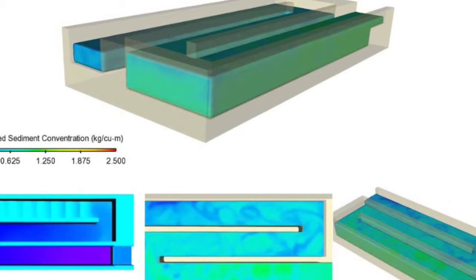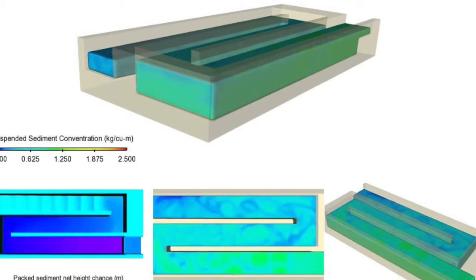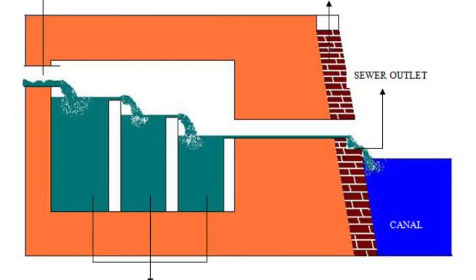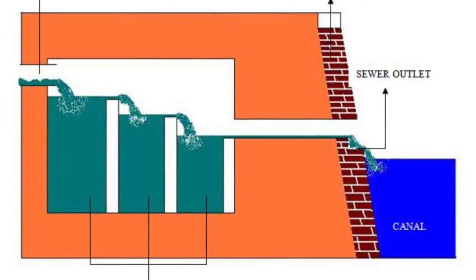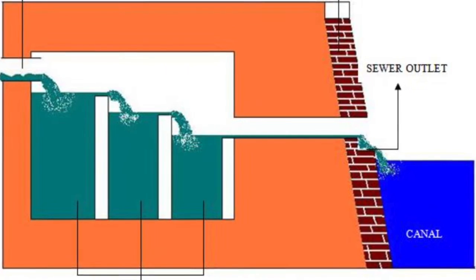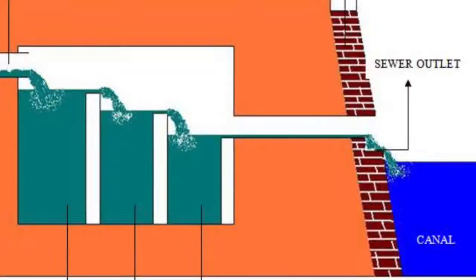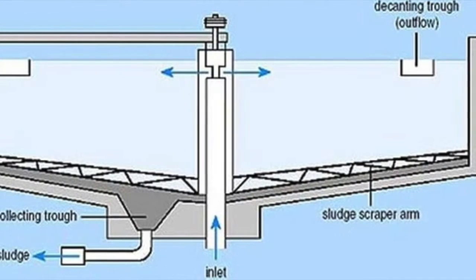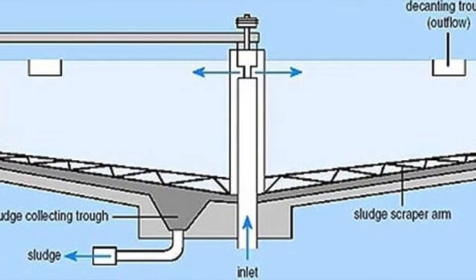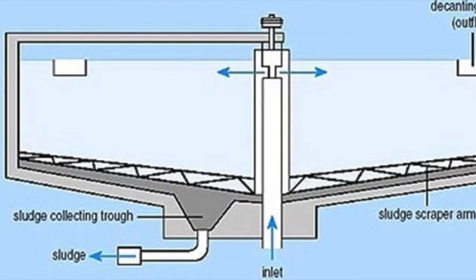Another common example can be seen in settling tanks that allow suspended particles to settle out of water or wastewater as these particles flow slowly through the tank, in the end providing purification. Turbulent flow would keep all of the particulate matter ingrained in the flow of the water. Furthermore, to solve this problem, by being able to use laminar flow, the particulate matter can easily drop out and flow out of the settling tanks.